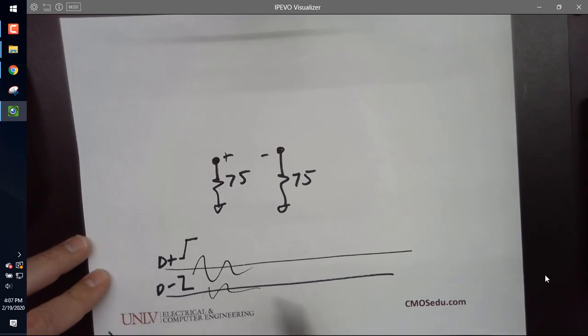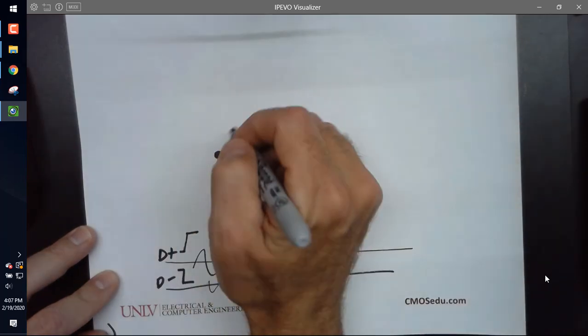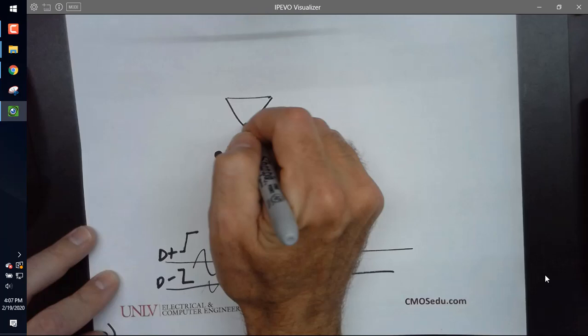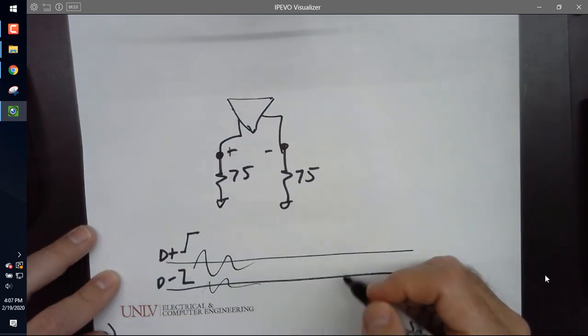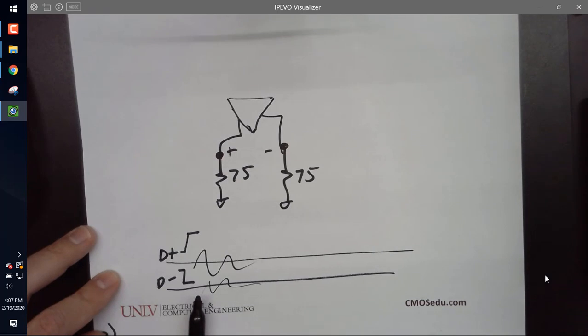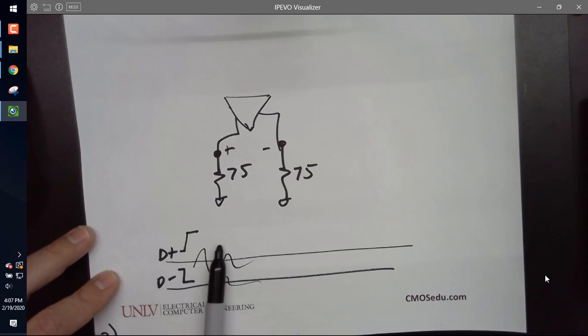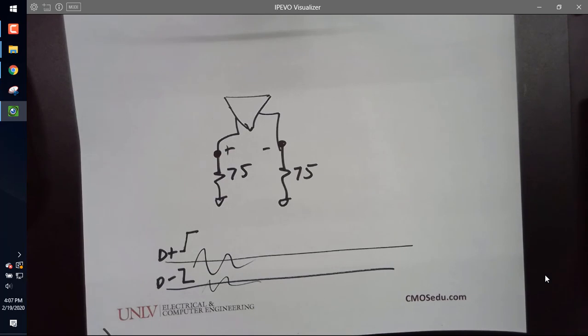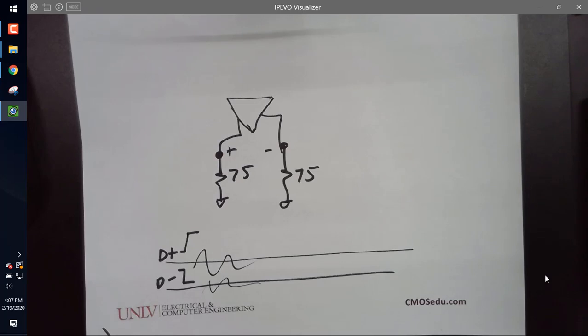Then you get the noise on the wire. When you get over to the receiver, there's a diff amp that takes the two outputs and subtracts them. So any coupled noise, like from a television station or a radio station, is subtracted when you take the difference. Only the difference mode signal gets into the circuit. So these signals are transmitted differentially. Has everybody got that? You want the picked up electromagnetic radiation to be coupled evenly into both lines.